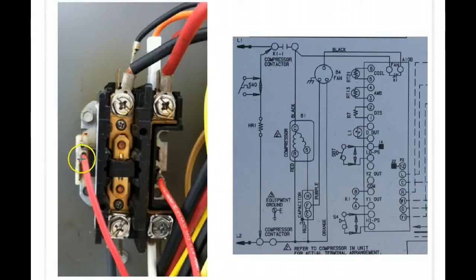Remember, we talked about that coil that energizes the contacts. Well, the voltage that is applied to this coil is applied on these two outer terminals right here. And if you look at the schematic diagram, you can see that there's that schematic symbol I talked about right here, the little zigzag. That is representative of the coil that is in this contactor right here.